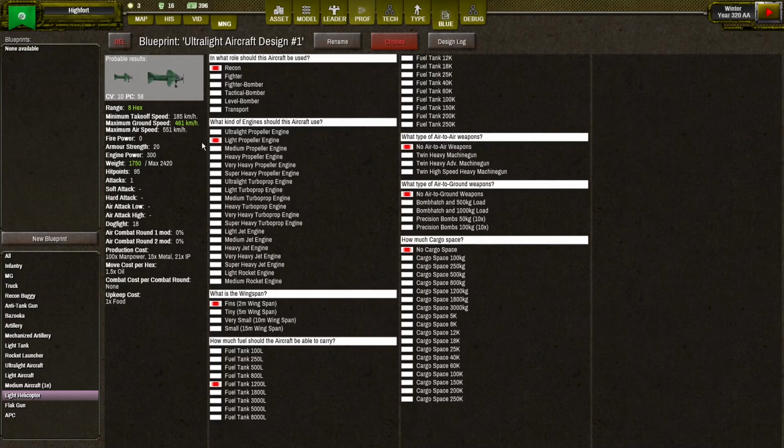If you have a high gravity planet, it will be much more difficult and you will need much more power from your engine. But instead of increasing engine power, I can decrease the first number. I can increase the wingspan, so to 5 meters long. And please look at this first number. From 198, I can decrease this number to 134.